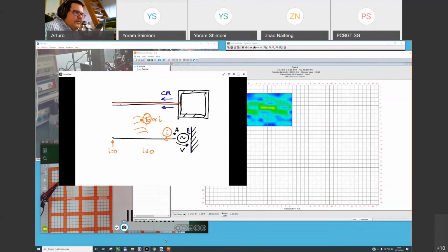How can you reduce the injection of this current? The first possibility is to go inside of your PCBs and to destroy the voltage, to make the voltage equal to 0. So there will not be excitation. In our demo, instead of doing this, making the voltage equal to 0, we need to go inside of the product. What I am going to put here is a ferrite.